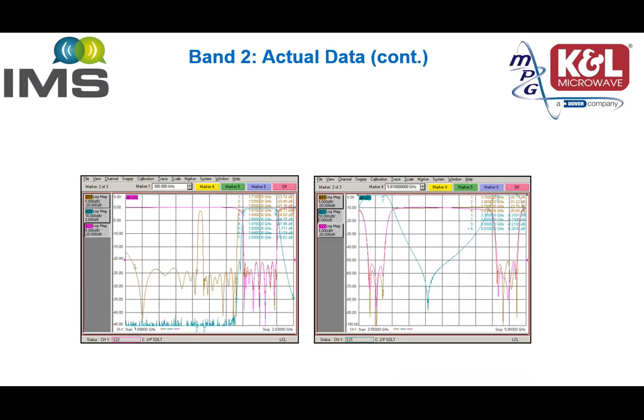The upper frequencies of blockers at 3800 and 5800 are passing through an additional diplexer shown on the graph on the right. Overall, we see that the return loss is nearly 17 dB, which provides a perfect match to the device under test across all the frequencies.